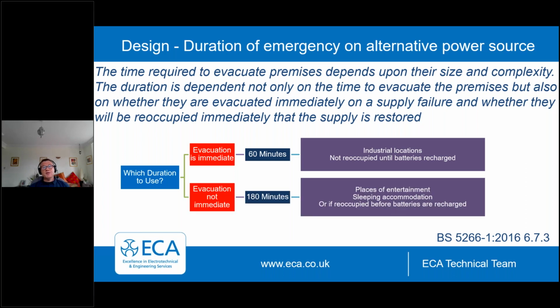Or the 3-hour one, where evacuation is not immediate, or evacuation may take a little bit longer. There are loads and loads of examples here, all in that section, but particular examples for the 3-hour location would be places of entertainment or sleeping accommodation. Or if you wish to reoccupy before the batteries are fully recharged and have a minimum of 1 hour in them, of course. So they are your options, and maybe some of the considerations that we need to make when deciding on which one to use.